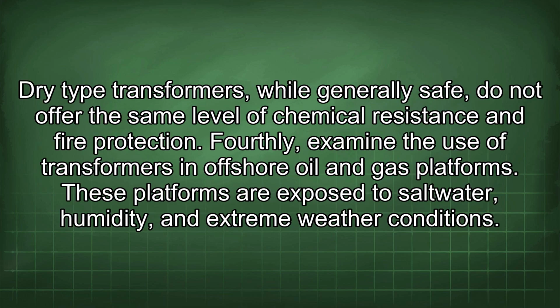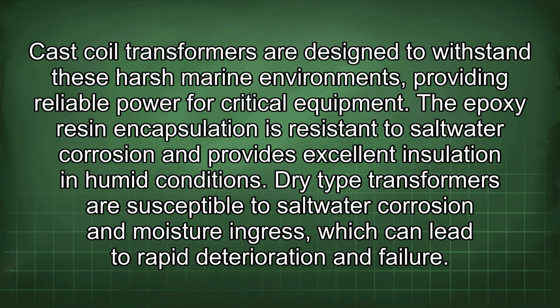Dry-type transformers, while generally safe, do not offer the same level of chemical resistance and fire protection. Fourthly, examine the use of transformers in offshore oil and gas platforms. These platforms are exposed to saltwater, humidity, and extreme weather conditions. Cast coil transformers are designed to withstand these harsh marine environments, providing reliable power for critical equipment.